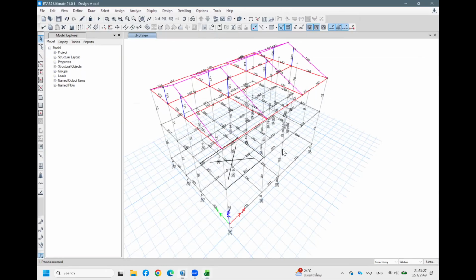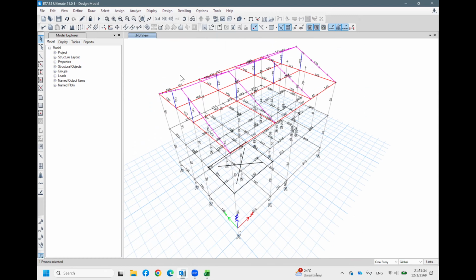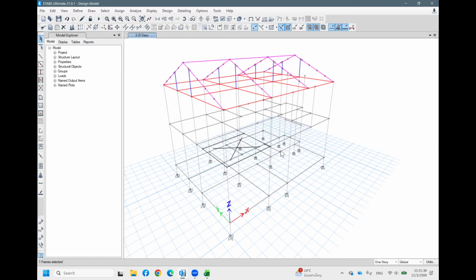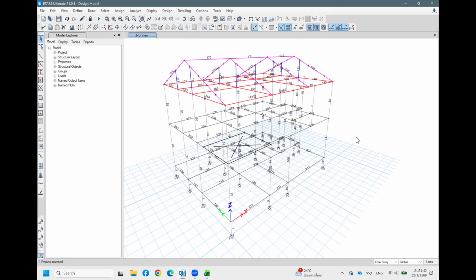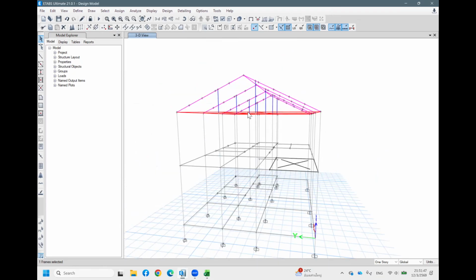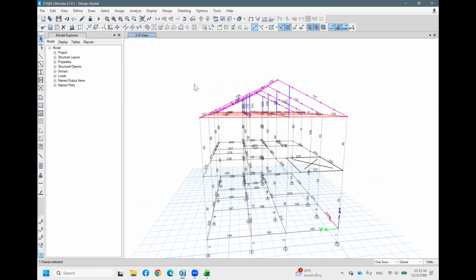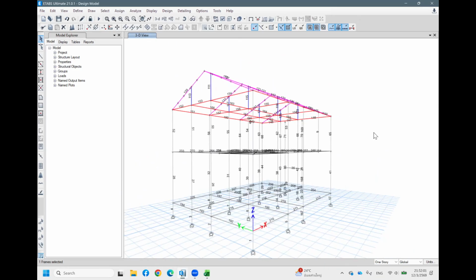However, I want to show you another method of how to design in ETABS by selecting the steel by yourself. For example, for the structural steel in the roof, we can check the capacity directly, and we can check if it passes or not. So if it passes, we can use directly the section that we define here. But for concrete it is a little bit different.